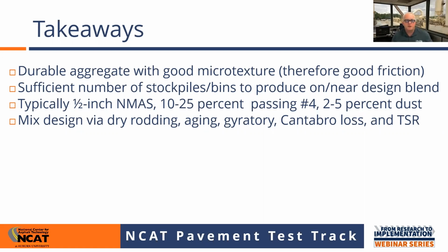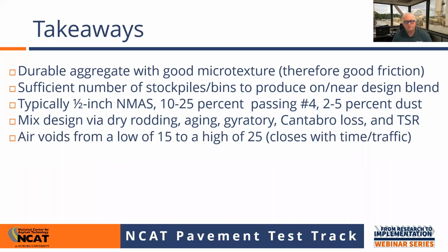So there's not a mystery about what your binder content is going to be. If you're in a state where the agency does not pay for asphalt separately as a separate pay item, and you do your mix design and you think you're going to have a 6% asphalt mix, and then now it's a 7% asphalt mix, that's a catastrophe financially. So you're not going into that blind. You can do all this in a contractor's lab because it's a very simple process.